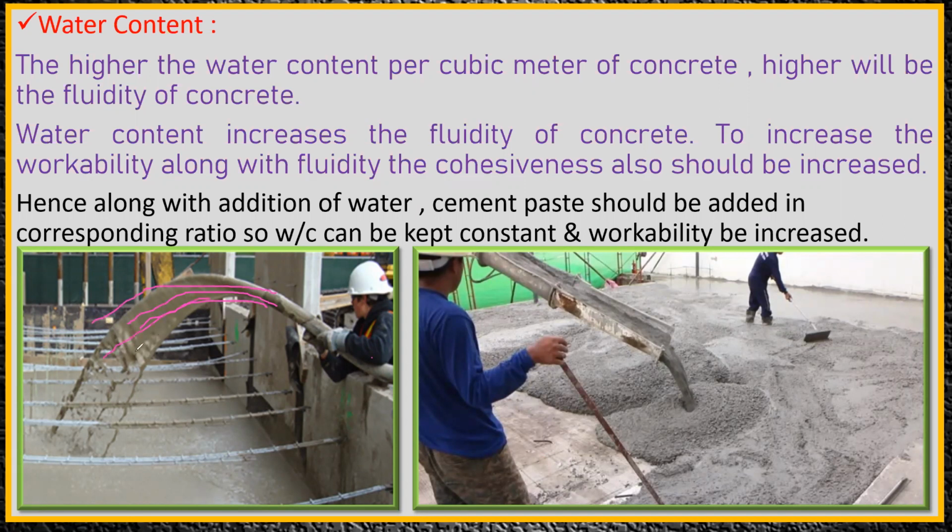Now what you can see, the water is coming out, whereas you can't see the aggregate and the cement, right? So there is a lot of water here. So here the fluidity is more. This doesn't mean that your concrete is workable, right? This concrete is no more workable. Even though there is a lot of fluidity, it's not workable in nature.